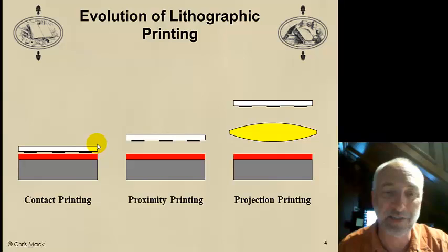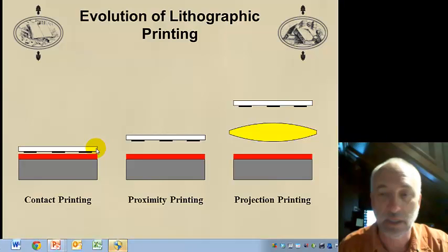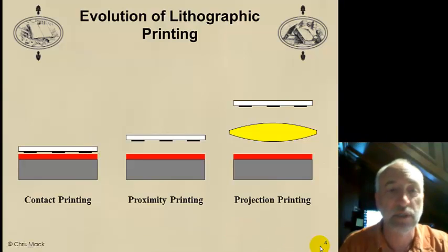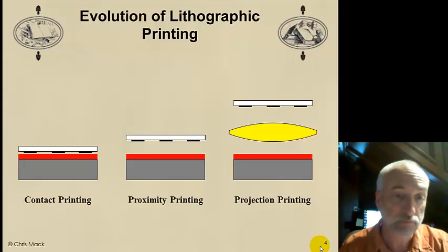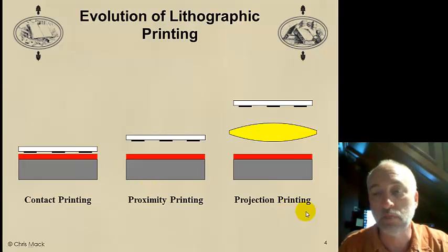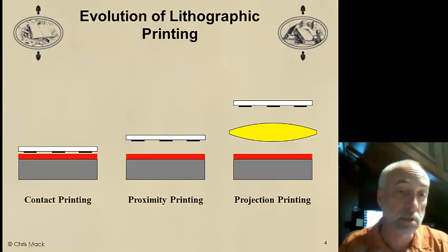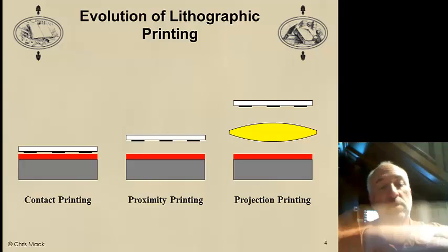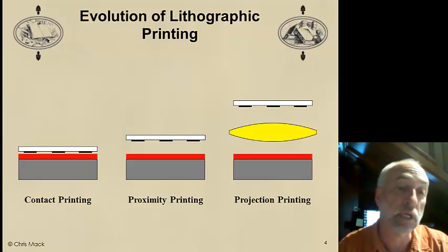We tend to say glass, but today it's fused silica. In some days past, it actually was plain old glass, with some absorber, some material that absorbs light, blocks the light. Today mostly chrome, but there were other materials used then and now. We put this mask in direct contact and we shine some light and we get a shadow print.